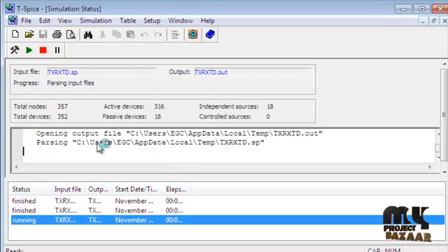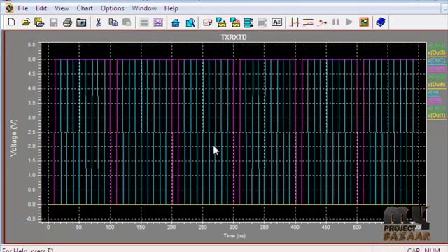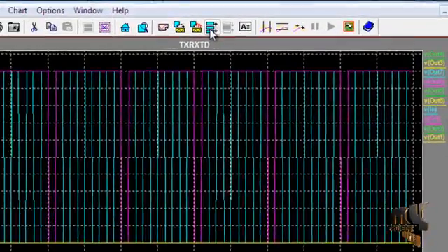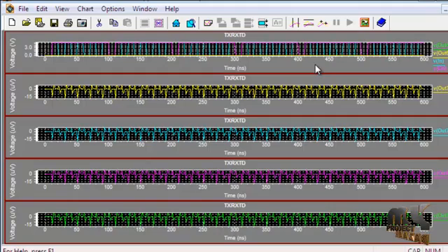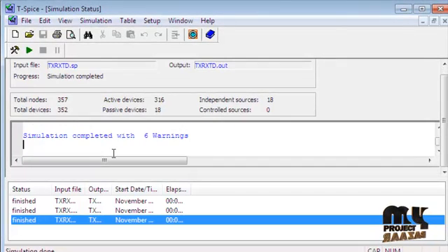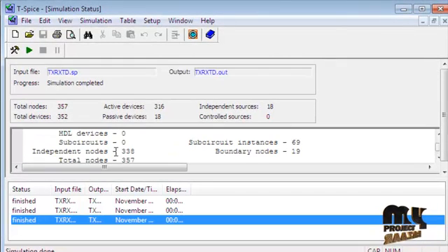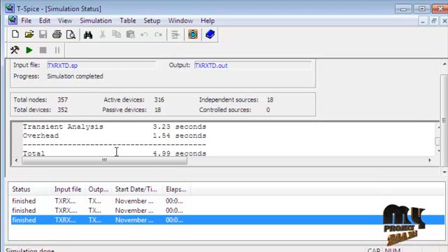In the tSpice window, the input data is shown, and this is the output data waveform, which comes from the WEdit tool. These are the overall output waveforms. If you want to view them separately, click the expanded chart, and the data will be shown in a separate view. This is the output waveform, and we are also able to calculate the power and time. This is the time waveform, and the time value is obtained in the tSpice window.